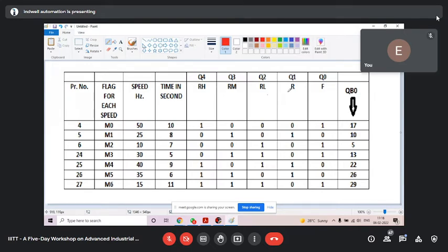Yeah. See, these terminals are on the AC drive, but its command we can decide. Whether I have to run the motor in forward or reverse, we can decide. So we have decided: first I shall run in forward, then reverse, then forward, forward, reverse, reverse, and again forward.